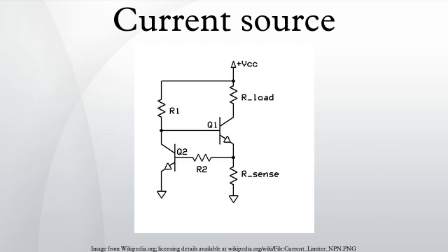Background. In circuit theory, an ideal current source is a circuit element where the current through it is independent of the voltage across it. It is a mathematical model, which real devices can only approach in performance. If the current through an ideal current source can be specified independently of any other variable in a circuit, it is called an independent current source. Conversely, if the current through an ideal current source is determined by some other voltage or current in a circuit, it is called a dependent or controlled current source. Symbols for these sources are shown in Figure 2.